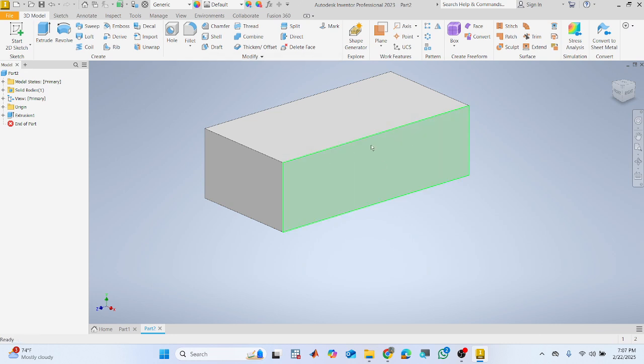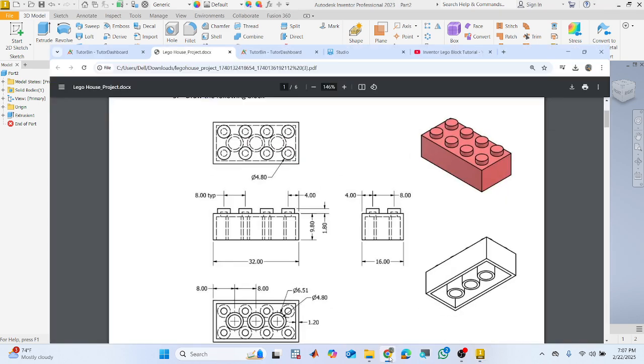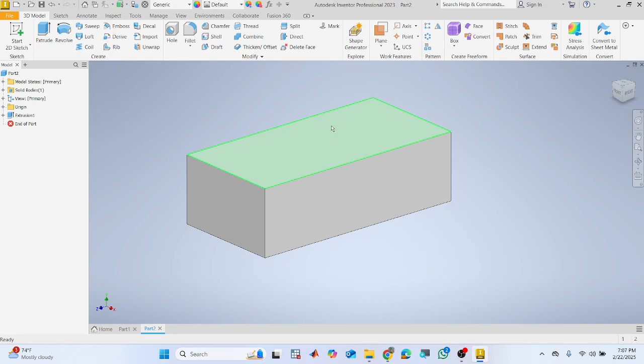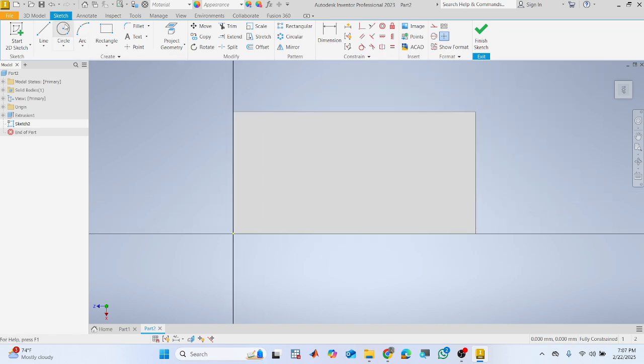Yeah. So 9.80, and it will draw something like this. Now we want to make these small hollow blocks. To make them, you have to click here and create a sketch. We want to draw one circle, and let's see, this is negative and this is positive. So x is negative, y is positive.